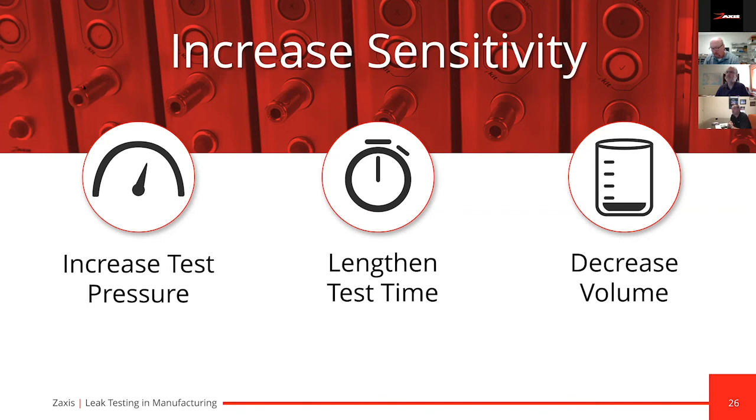So some people will link a pressure decay test with a vacuum decay program and do four or five of those. It can be real quick: give pressure, pull vacuum, give pressure, pull vacuum. That exercises the part and may get a catheter balloon inside a sheath to move a little bit, so that you can detect a very small pinhole in a crease that you may not have seen the first time. So I just thought I'd add that in.